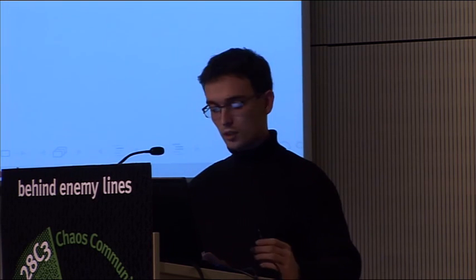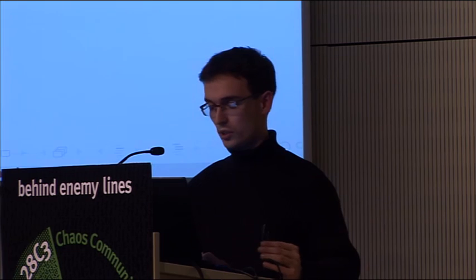Yeah. You mean through JTAG? Have you seen some JTAG lines, or have you looked for this? I have not looked for this. I know there is a JTAG which is connected directly to the ARM processor, but to the flash, I don't know. I have not looked into it. Okay, because it would be interesting to do this. But you can reflash the NAND through software calls, so you do not need hardware.